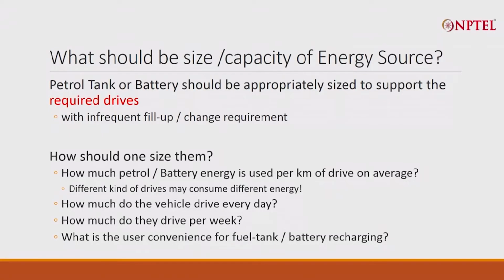In a very similar manner, you will say how much battery energy is required per kilometer on the average, and you say okay, so much distance you want to travel. So this is the size of the battery that you need on the average. Of course, remember I talked about different kind of drives will require different amount of energy. If you are, for example, climbing a hill, of course the energy requirement will be much more. So you won't be able to go the same distance. So some kind of average that you will take.